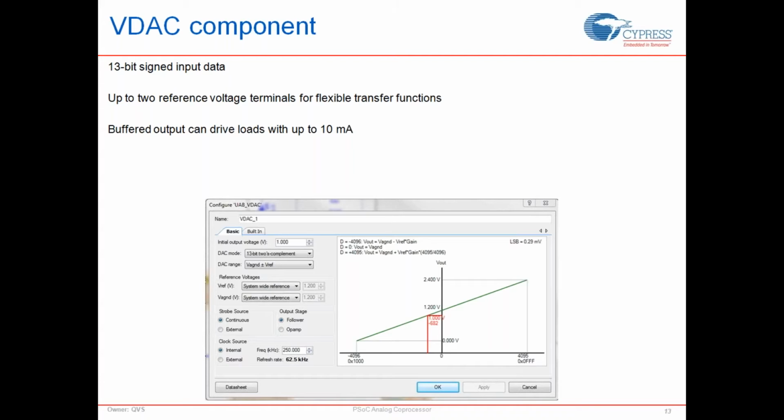as in you want a more uniform update to your VDAC so that your update frequency is consistent. The reason you want consistent update frequencies is that most times, if you're trying to do waveform generation from the VDAC, your update frequency is something you want to keep constant so that you can filter it out, because it shows up as a spike in the spectrum of the output of the VDAC. So generally you would have a filter on the output of the VDAC that filters out the update frequency, or the sampling frequency, of the VDAC.